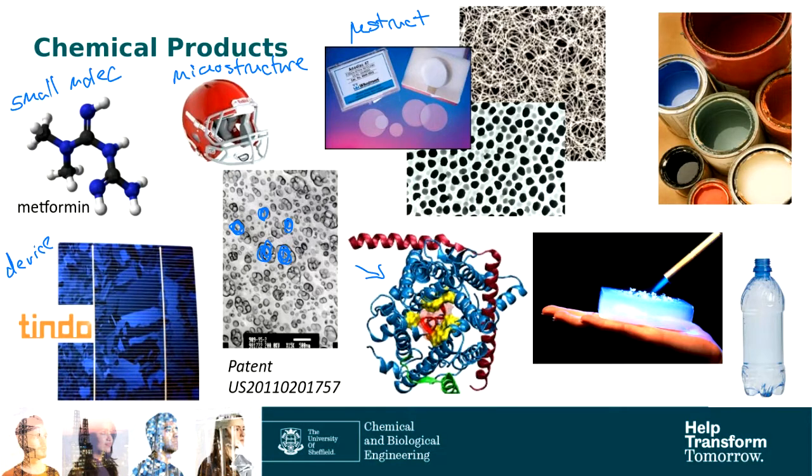And these are those materials that are something like 99% air and just 1% solid. And so what you see is that a person doesn't feel a flame on one side of the surface going through a centimeter thick of this material. That's because it has a very, very low thermal conductivity because it's mostly air, and air has low thermal conductivity. So this material gets all of its commodity value from being microstructured.